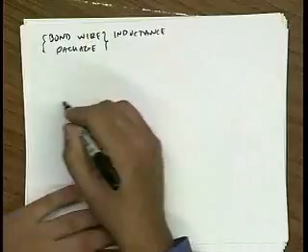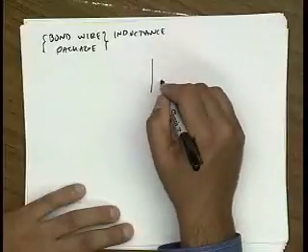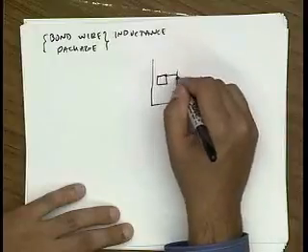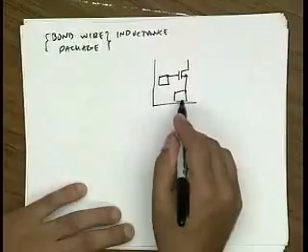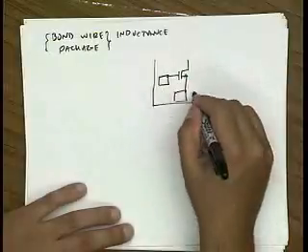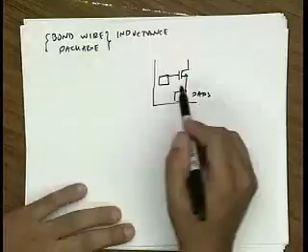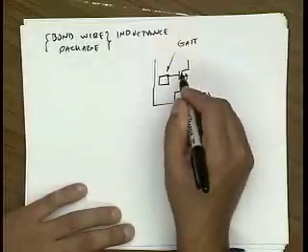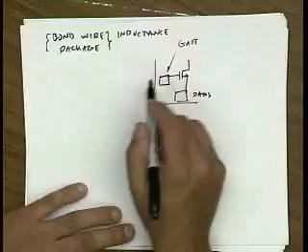That means that you have to go from a board to a chip. And that interface, drawing it very crudely again, involves going through lots of parasitics. So here's my transistor input stage. And I want to connect this to ground on this side and to the signal on this other side. But realistically, because these are pads, and these pads have to interface with the external world, especially here, this is a gate. This touches the gate. This is very electrostatic sensitive. Small voltage here can easily destroy this device. 10 volts will basically destroy this device.